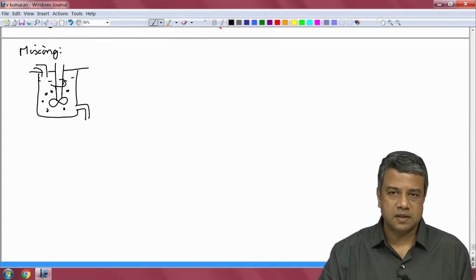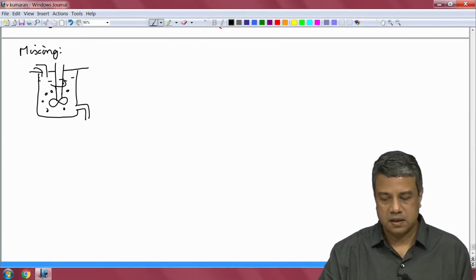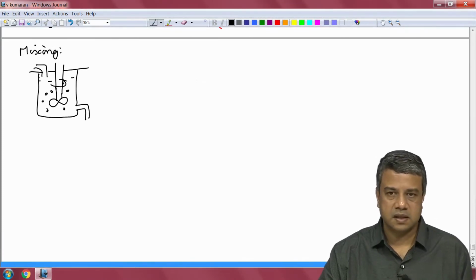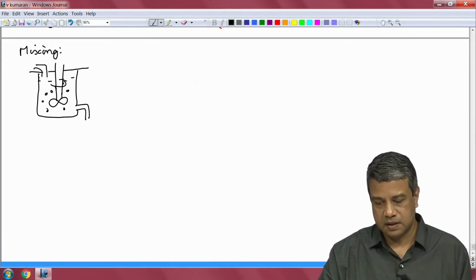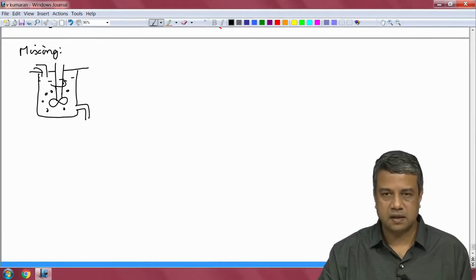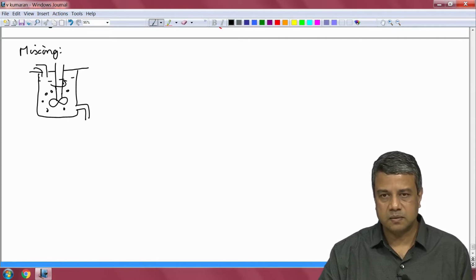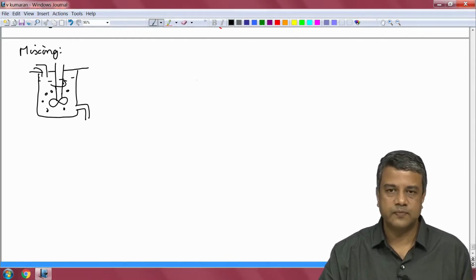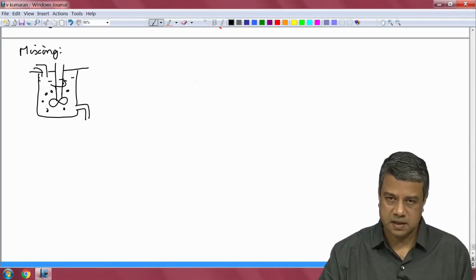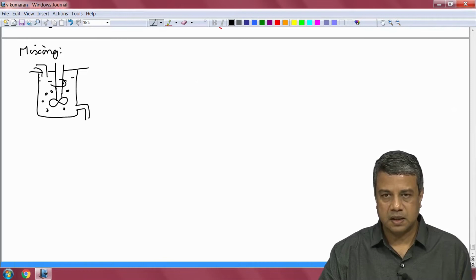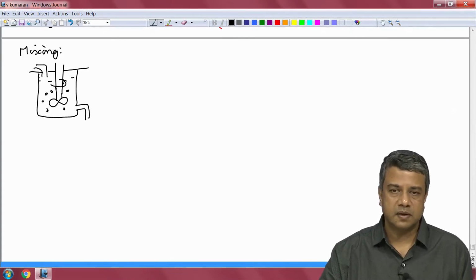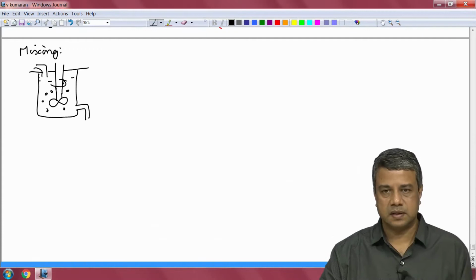In this lecture, we will look at a simpler question, that is, if I wanted to design a large scale impeller setup, you could either try to actually calculate the velocity profiles everywhere, which is a complicated exercise. Another way you could do it is to build a smaller scale model of the impeller and try to see what is the power consumed in that scale model, and based upon that try to calculate what is the power that would be required for the actual impeller.